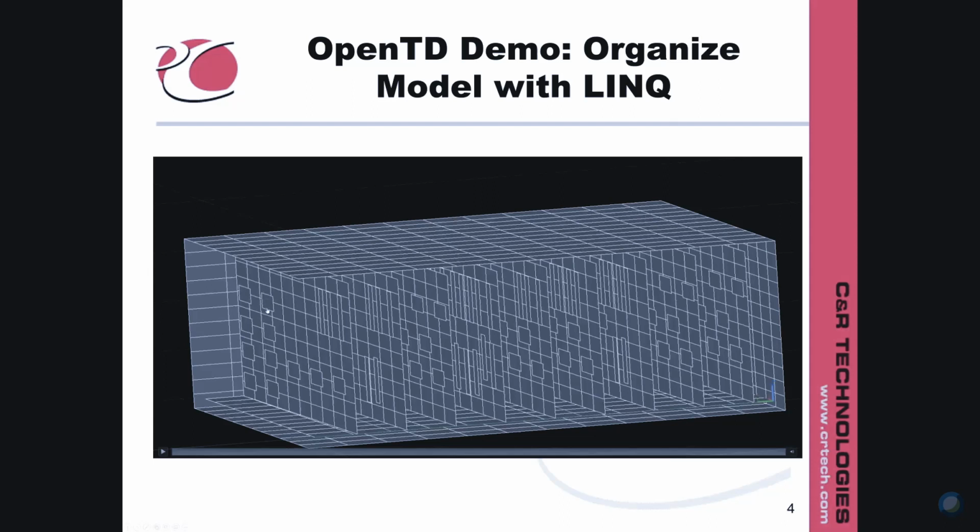So we can say, hey, get me all of the rectangles that have material aluminum and stuff those into a list of enclosure rectangles. And get me all of the rectangles that are this dimension, and that's going to be such and such a chip. Put that into a list of chips. And then apply a heat load to those chips, but make a symbol control that heat load. So we can do all that stuff.